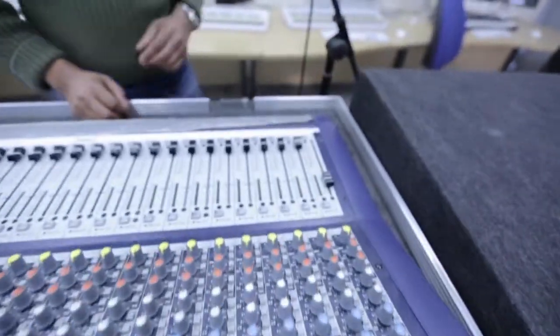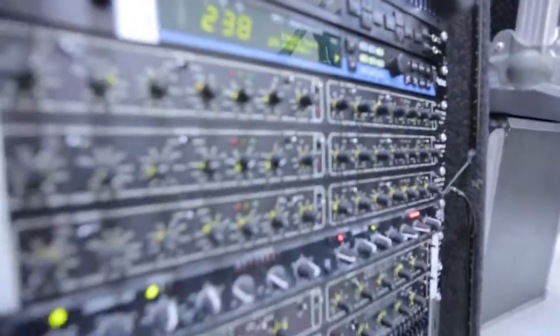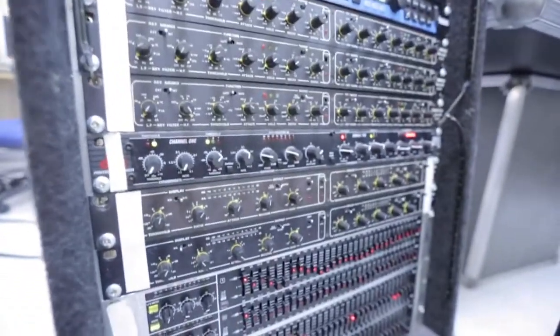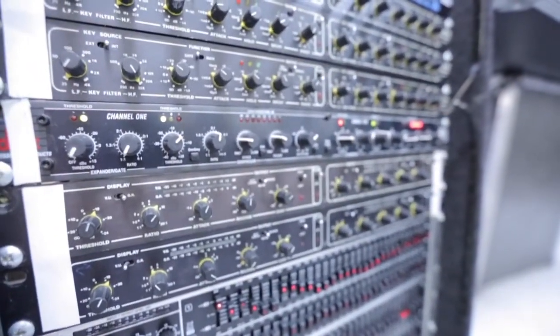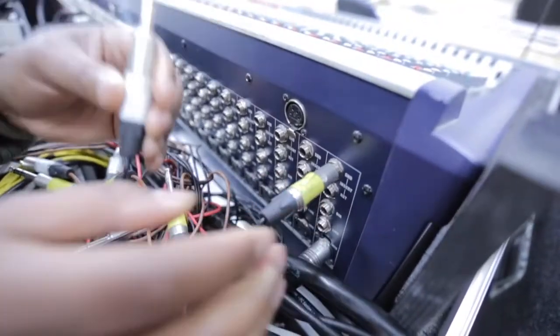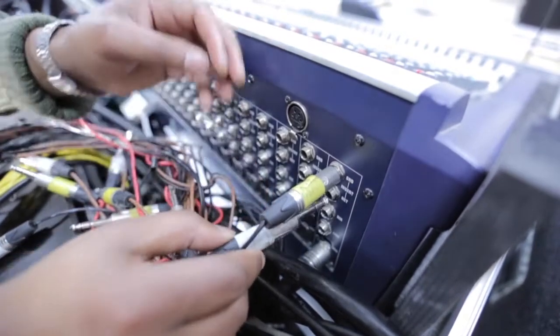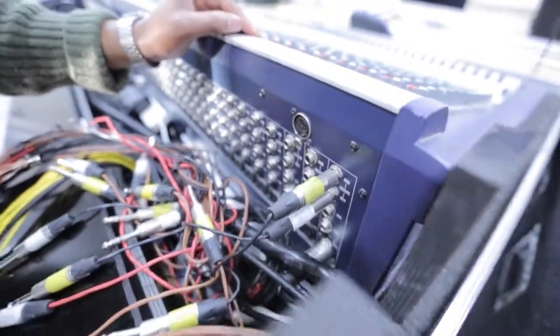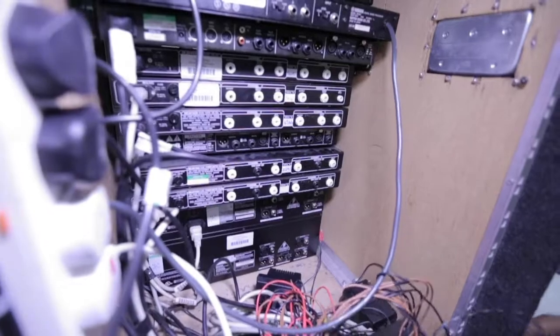The effect rack contains graphic equalizers, compressor gate, reverb, and other effects units. I'm going to connect the compressor to an individual channel. Here, I will connect the jack labeled 1 to the channel 1 insert send, and take the jack cable connector labeled 2 and connect it to the insert return. This will send the entire signal into the compressor and back through into the return.